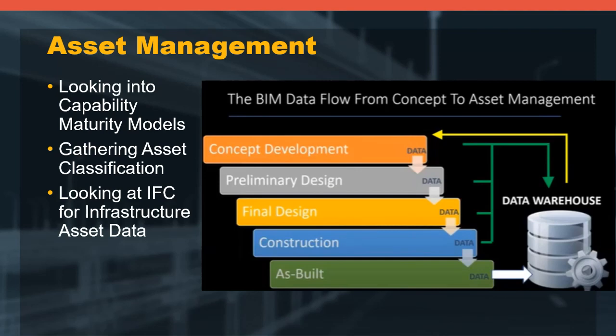Bill Pratt from Connecticut DOT has been looking at the asset management perspective of all of this. Because at the end of the day, what you want to be able to do is create a digital as-built that can then be harvested, taking that information out of the as-built and putting it into your asset management warehouse, and/or various warehouses that you use to manage your assets throughout their life cycle. I think we all know there's a ton of information gathered during construction that either isn't always captured or isn't captured in a way that makes it accessible across the enterprise. So we're looking at how you do that. How do you capture that information? Number one, what information do you need to capture, to what level of detail and accuracy? And then how do you spread that throughout your agency so that you can manage those assets better.